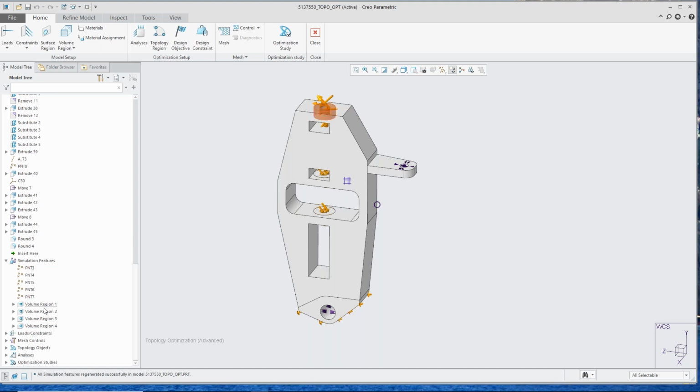And again, this is brought from mechanism dynamics, where we can do that. We can just pick surfaces and constrain them and load them the way that we want. In this particular example, it's just brought in from that capability. But one of the things it does is we create volumes, all right? So we see there's some volumes here. As I move my mouse over them, we can see them highlighting in different areas. That tab is a volume, this bottom area is a volume. Now, in typical FEA analysis, when we specify a volume, we might say, well, this volume has different material in it, or this volume has a different density of mesh or something like that. In this case, when I specify a volume, it's like, don't mess with this geometry.